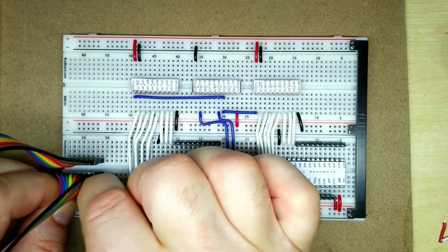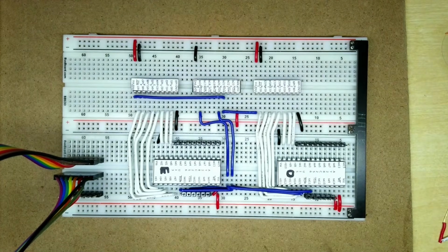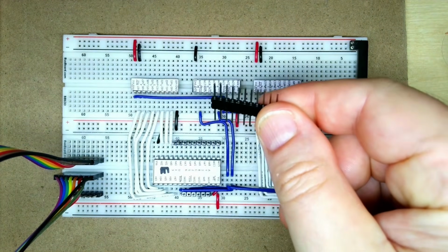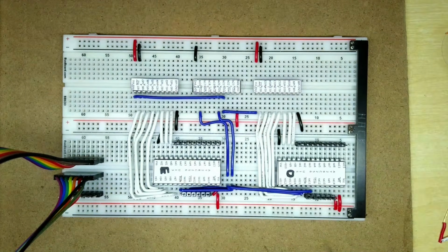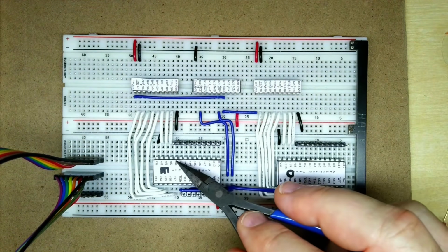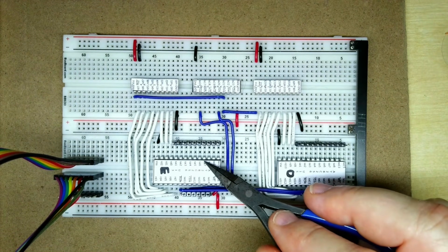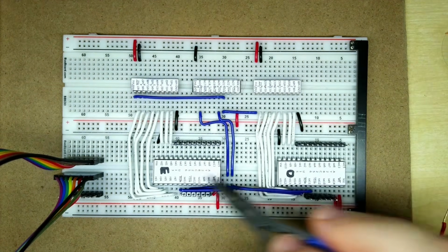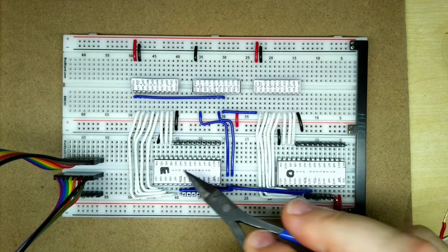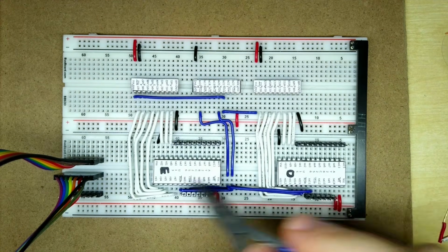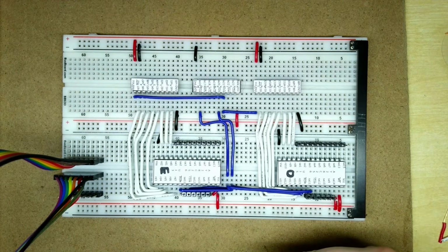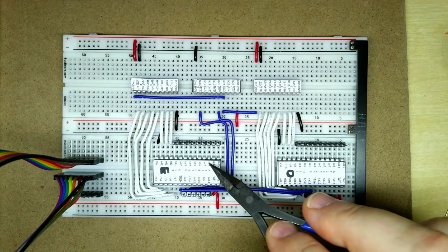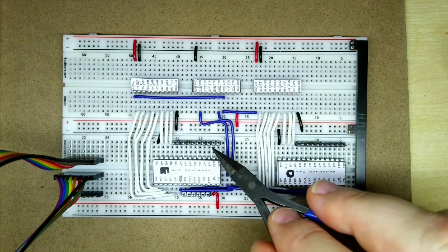This is an 8-way connector, and I've actually got an 11-way connector here. The reason for that is that in addition to 1 going to 7 there, we're missing out 0 because we've got 16 bits, not 8 bits. So SA0 is not relevant when we're dealing with 16 bits. But we need to have the 8, 13 and 15 populated.